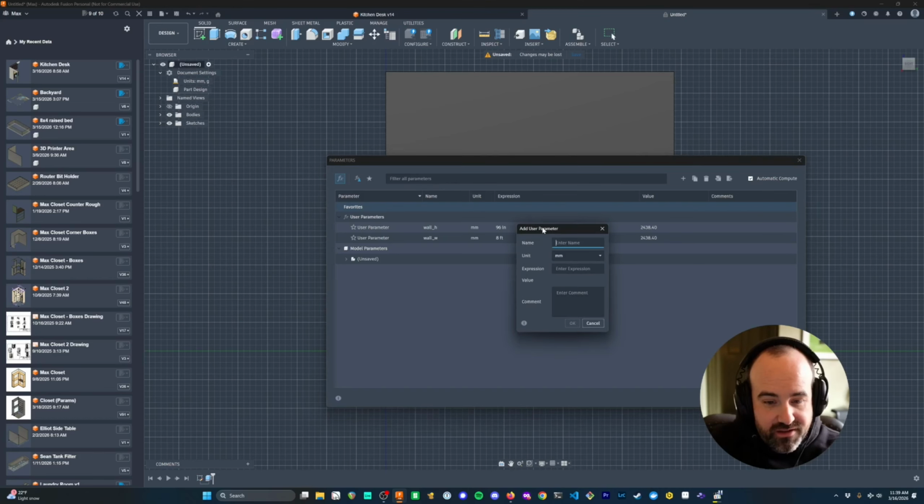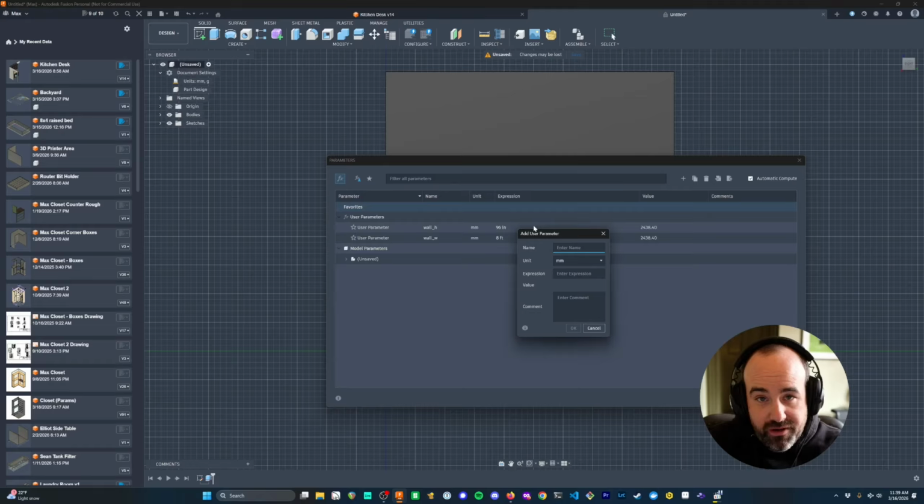In this case, most 3/4 inch plywood in America is about 18 millimeters or 19 millimeters. I've found that the standard stuff like birch, cabinet grade material, pre-finished birch, it's 18 millimeters. If you get something like a hardwood veneer, like a walnut, higher end expensive stuff, the stuff I've bought recently has been 19 millimeters. And so, just pick, and if you're using half inch, or 12 millimeters, 13 millimeters, you base it on the thickness of your material.